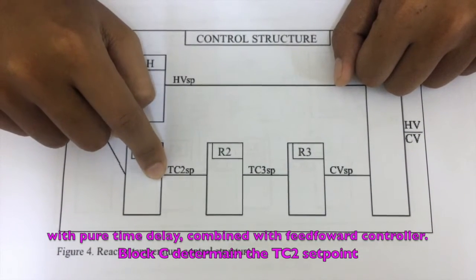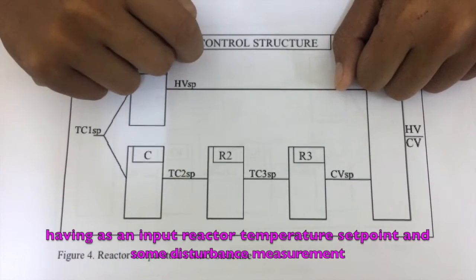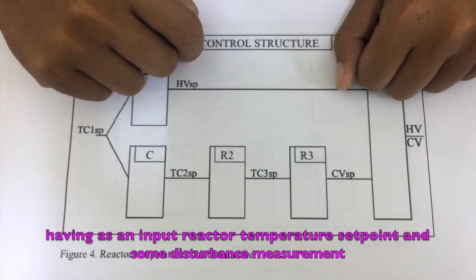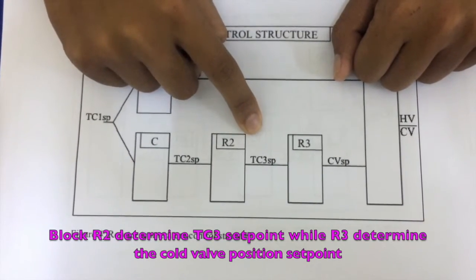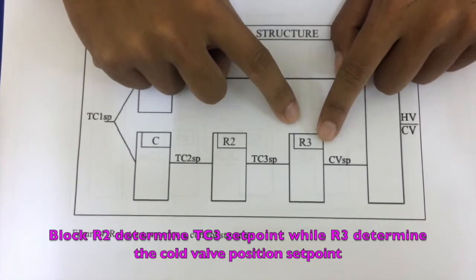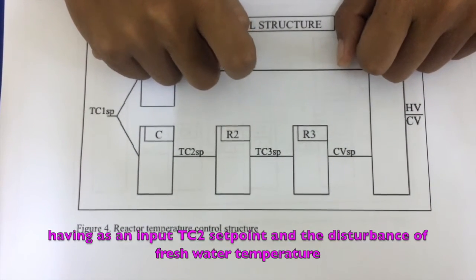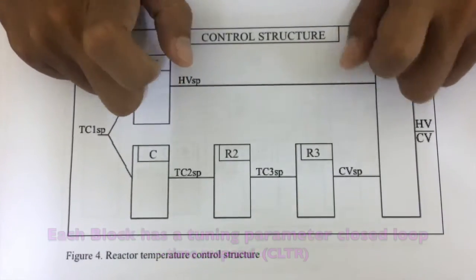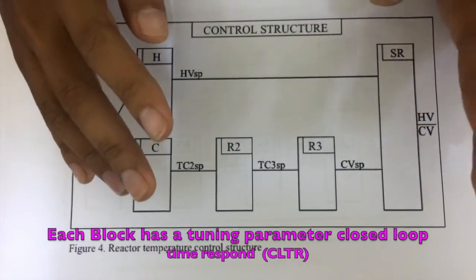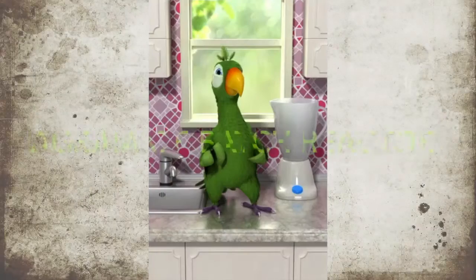Block C determines the TC2 set point, having as input the reactor temperature set point and some disturbance measurement. Block R2 determines the TC3 set point, while R3 determines the cold valve position set point, having as input the TC2 set point and disturbance with flow of fresh water temperature. Each block has a tuning parameter, the closed loop time response, CLTR.